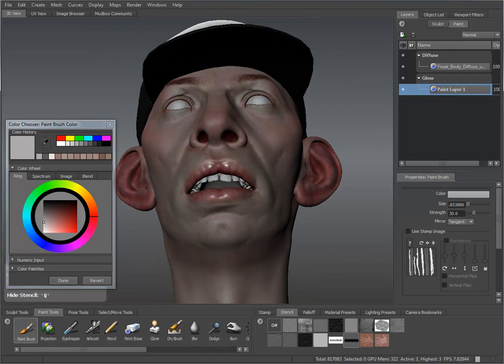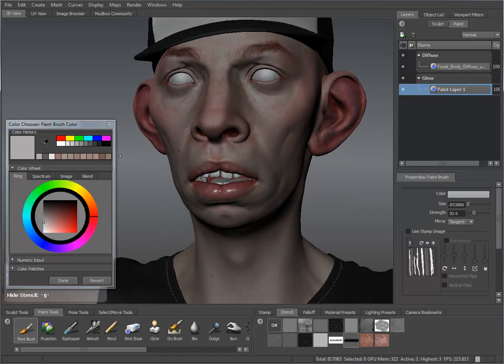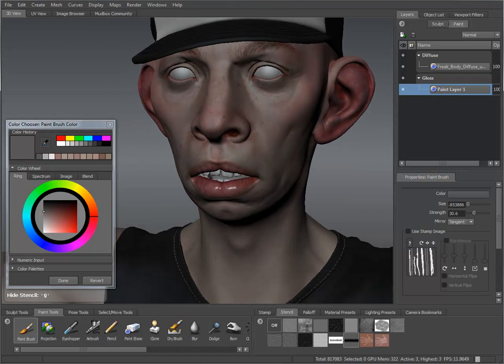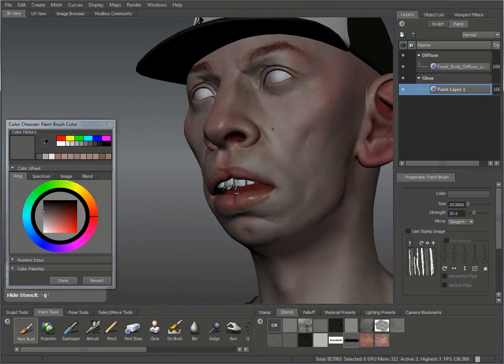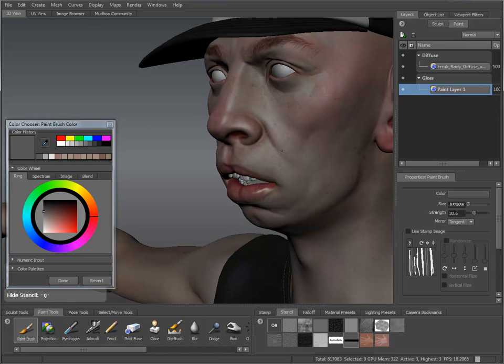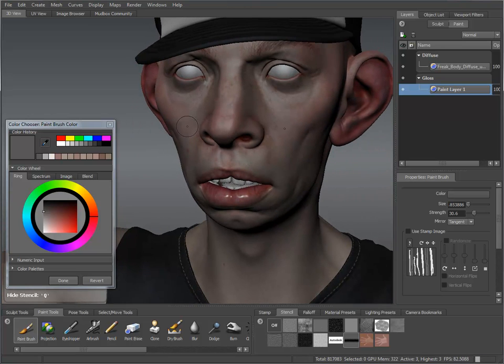I prefer using the glossiness instead of specular strength channel. The more glossy a part of the object is, the stronger the specular anyway, so you don't really need to paint a specular strength map, although sometimes it could be very useful also.